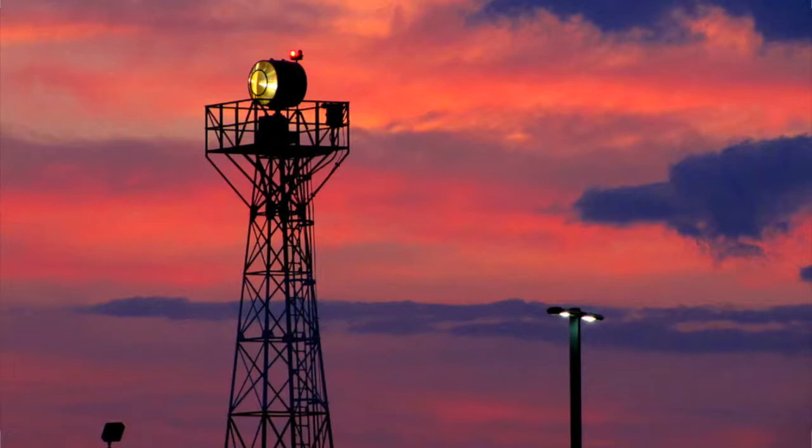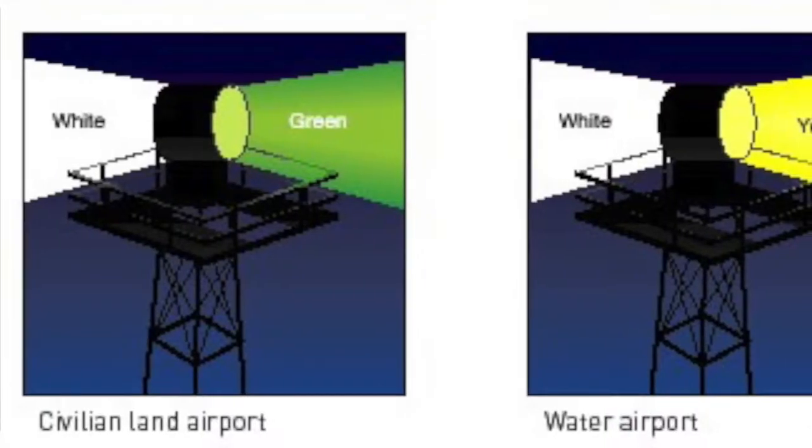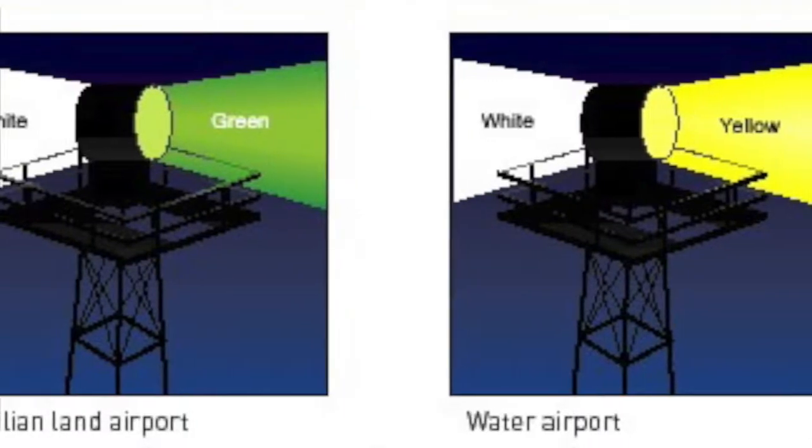But that is not a detailed flight path. You're just flying towards the direction of Toronto Pearson Airport. As you're getting closer and closer, you will notice that that point is just the airport beacon location. You then need to plan your landing route to make sure you're actually landing on a runway. Public use airport beacons rotate green and white.